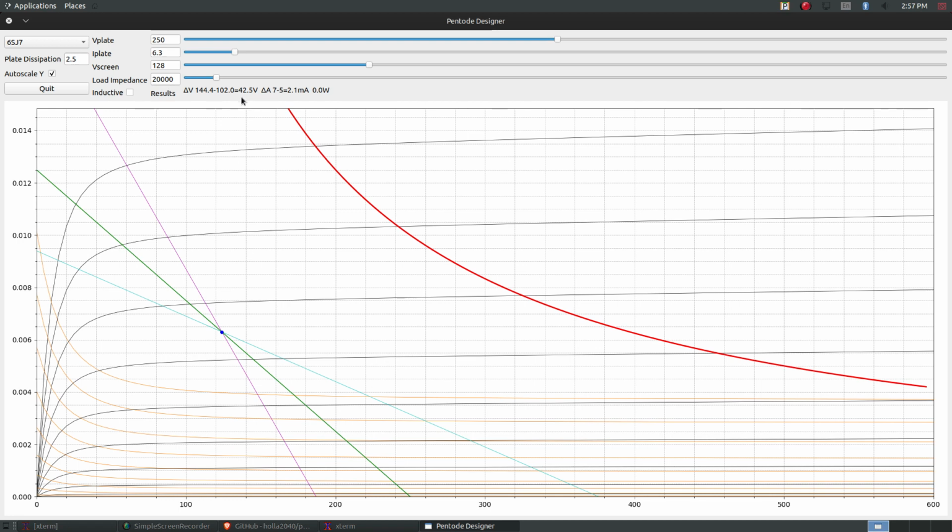If we want to make that gain a little bit higher, then we probably need to change this slope a little bit, and then move our load line back down like here. So a 1 volt drop across here would be from here down to here on the load line, and that's now 57 volts, which means our gain is now 57. This is all voltage gain.